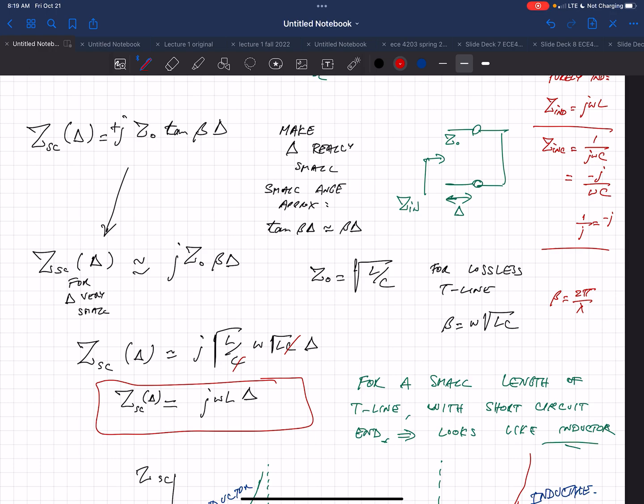You're going to get one maximum voltage and a minimum voltage, and as you keep going back away from the load, a maximum voltage and minimum voltage, then a maximum and minimum again. The period of that depends not just on how far you're going away in centimeters, but on how far you're going away and what the frequency of your input is.